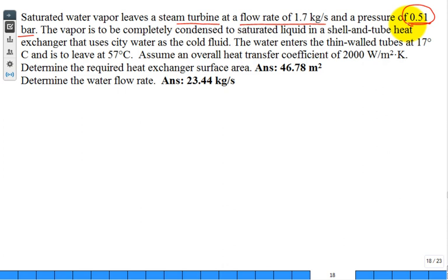0.51 bar? It is. So, yes, you can have steam within pipes, but if you pop a hole in the pipe, air would rush in and not steam rush out, because it's in a state of vacuum in that pipe. At 0.51 bar, it's in a state of vacuum.